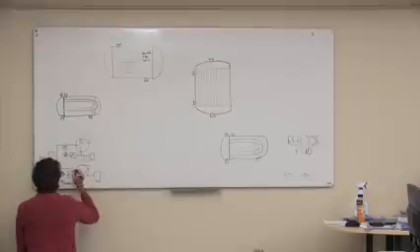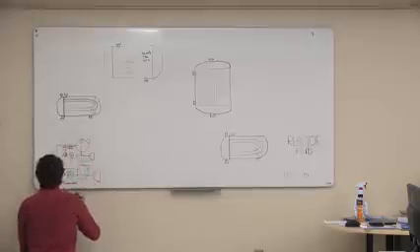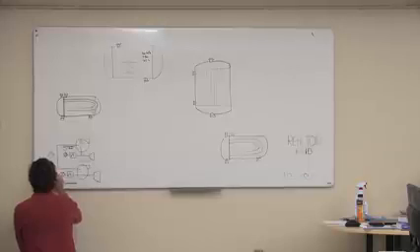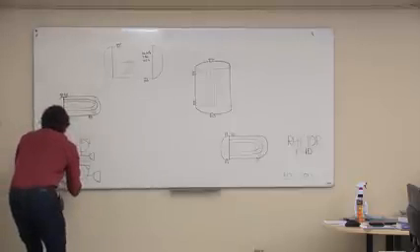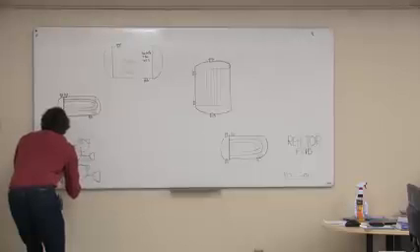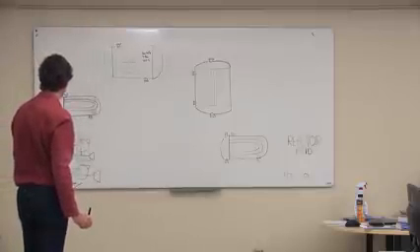When it's in auto, that allows the DCS to start and stop it. On, off, auto, like that. And then we also want to know whether we want to be able to start and stop the pump from the computer control system, the DCS. And so we're going to put an HS with a box and a circle around it and a line through it, like that. So that gives us the basic controls for the electric motor there.